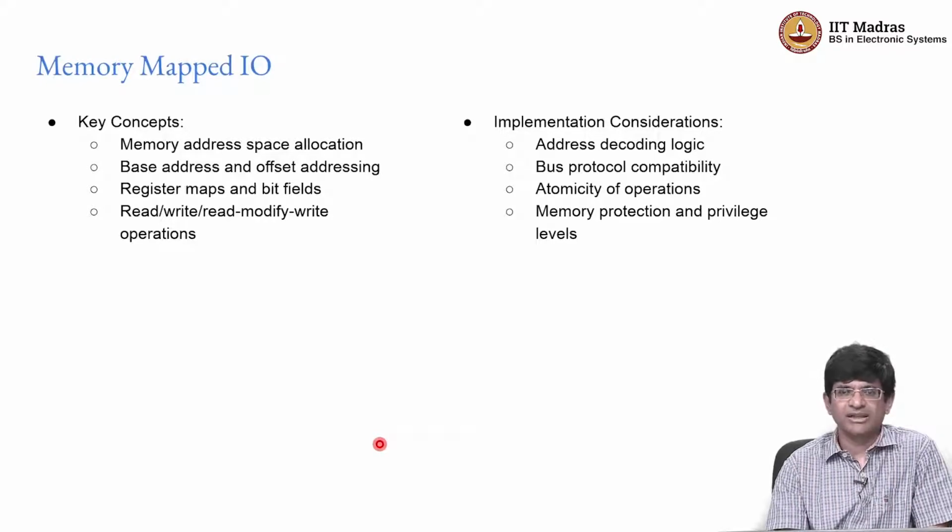So keep in mind that all of these ultimately come down to various kinds of specializations that can set your design apart from somebody else's, right. If you find that there's an application where having separate IO instructions makes more sense than having a memory mapped interface, then that might actually give you some kind of an edge or superiority over other kinds of designs that exist.